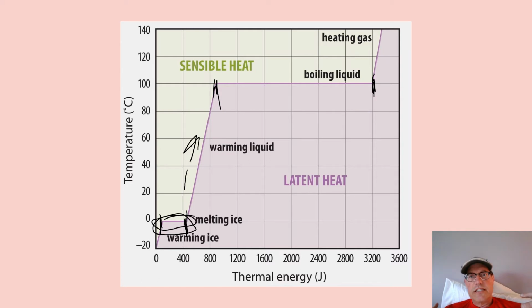That's why you start out as a complete solid, and then when you gain enough heat, it's a complete liquid. And then from there, it starts to change in temperature again, to heat up again, until it gets to that point of boiling. Well, when it's done boiling, you have a whole bunch of steam. Imagine that you could contain this steam. You'd have a whole bunch of that, and you'd still have your heat source. You'd be heating that vapor up into a steam, which is a high temperature gas. So it's very important to understand the latent heats. No temperature change is going on. The particles are gaining that energy, but they're using it to spread apart, get further from each other.